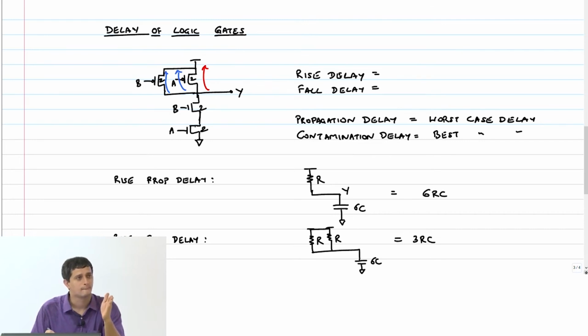Bottom transistor, suppose that input was high for long enough and it has discharged that intermediate node X to ground already, right? Then the output Y needs to be pulled down to ground, that's all. As opposed to if the A input also had to discharge the node X to ground, then it's both these nodes that have to be discharged to ground at some point.